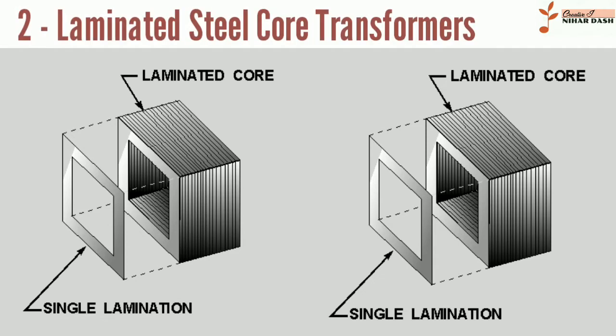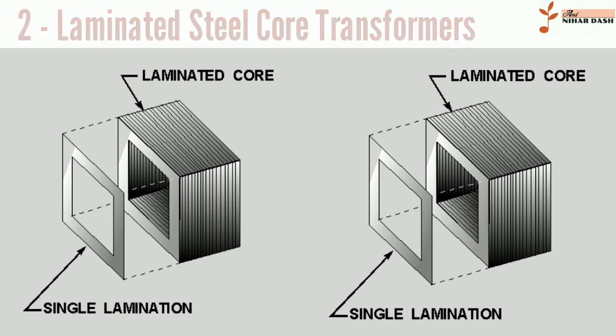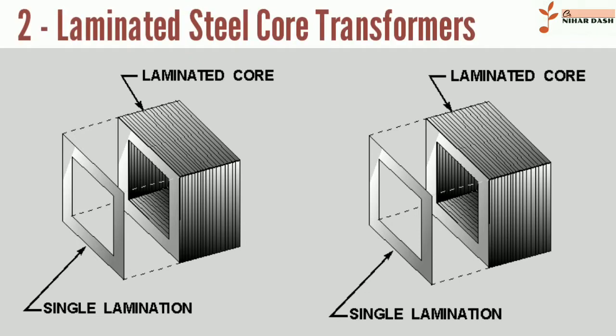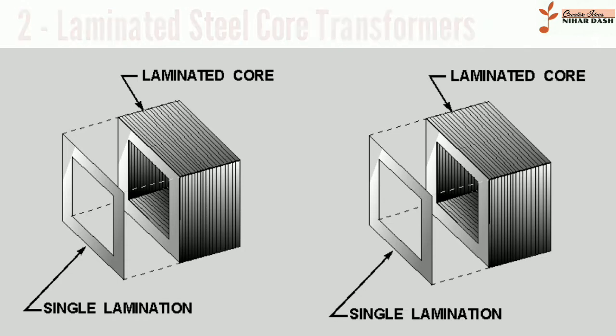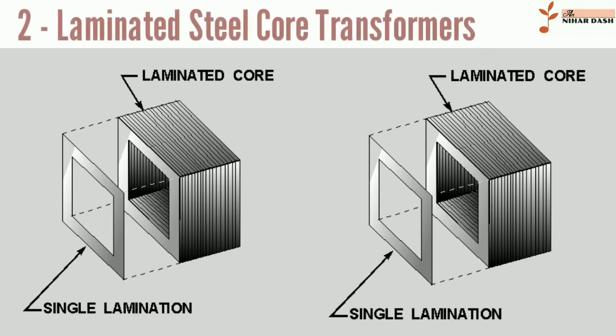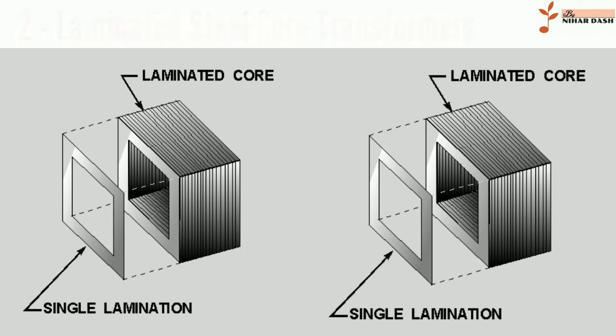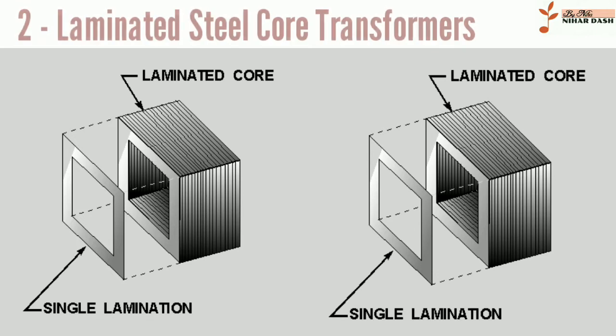When power is then reapplied, the residual field will cause a high inrush current until the effect of the remaining magnetism is reduced, usually after a few cycles of the applied AC waveform. Overcurrent protection devices such as fuses must be selected to allow this harmless inrush to pass. On transformers connected to long, overhead power transmission lines, induced currents due to geomagnetic disturbances during solar storms can cause saturation of the core and operation of transformer protection devices.